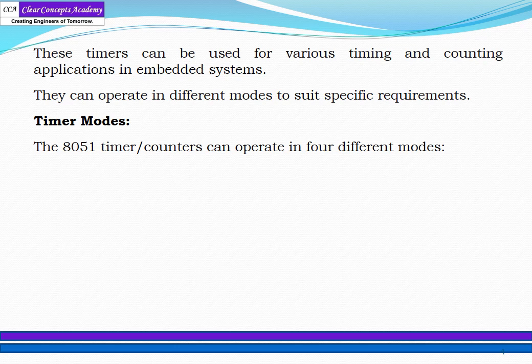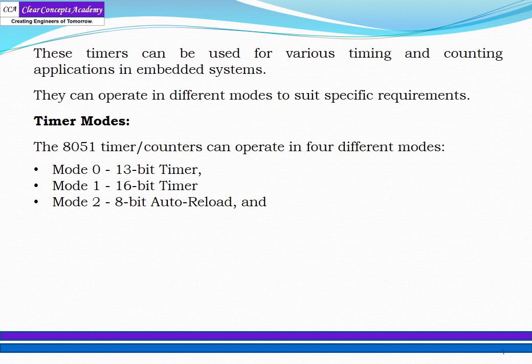The 8051 timer/counter can operate in 4 different modes. First is mode 0, that is a 13-bit timer. Then mode 1 is a 16-bit timer. Mode 2 is 8-bit auto reload, and lastly mode 3 is split timer mode. We will see all these modes in detail in our subsequent slides.